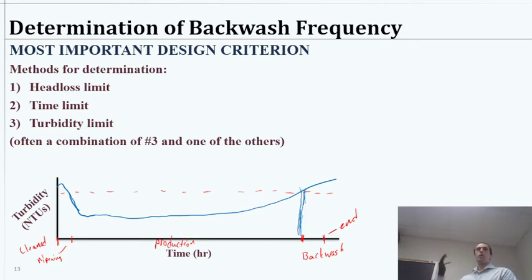So that would be how our turbidity limit would work. And that's probably a reasonable picture of how the turbidity would look in a backwash, in a typical system, right? During our rinse, we are over the limit here during the rinse phase, some amount over the limit, and that's a problem, so we don't use that water.